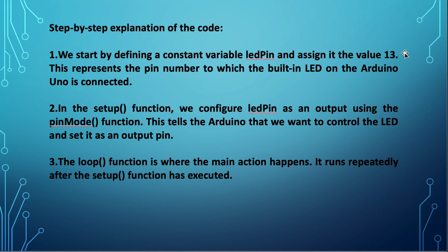Why? Because in Arduino Uno, we can select 13 as an input or output. But if it is not Arduino Uno, if it is a different board, pin number 13 could be different, right? So you have to see what kind of board you are using. These are small things that you should remember when doing your project, right?